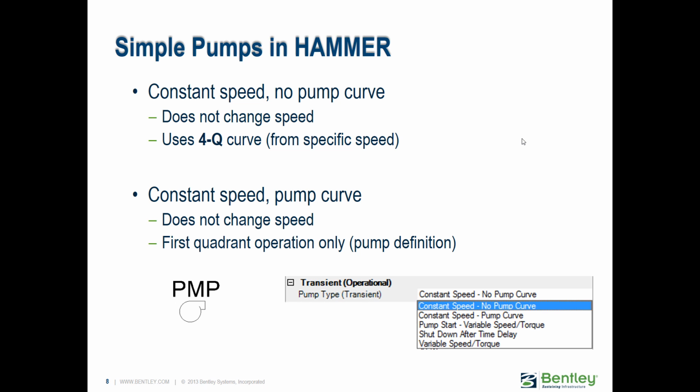So, simple pumps in HAMMER. There's a little screenshot at the bottom that shows you the different types of transient pumps that can be represented in HAMMER, and that's a little drop down in the pump properties. If you have a pump that isn't shutting down, isn't starting up, isn't moving during the transient simulation as far as the speed or the torque, then you have two different constant speed options.